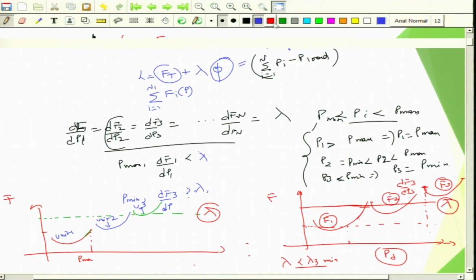So this particular unit 1 generator has its lambda minimum and it has its own specific lambda maximum. You can see here the actual lambda that you were able to find to meet the constraint, summation of generation equal to total demand, is this lambda.